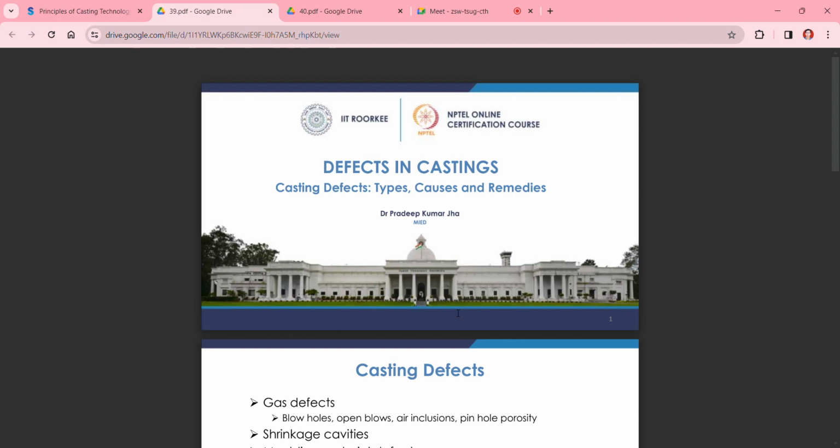However, the final casting dimensions are going to be changed, but you can provide some treatments for removing those defects. But if the defects are inside the castings, how are you going to check them? Because you have not seen the inside defects, and those inside defects are going to create problems during the life cycle of that casting, wherever you have employed that casting.